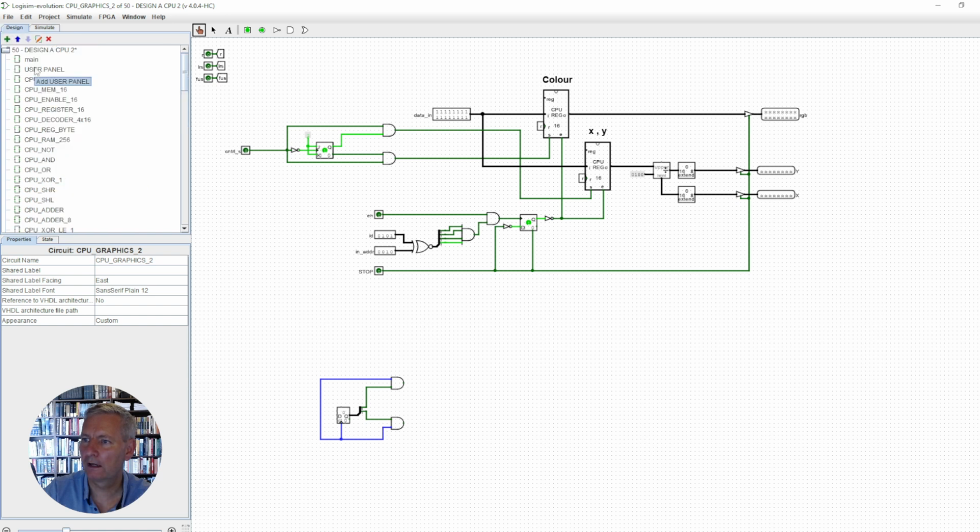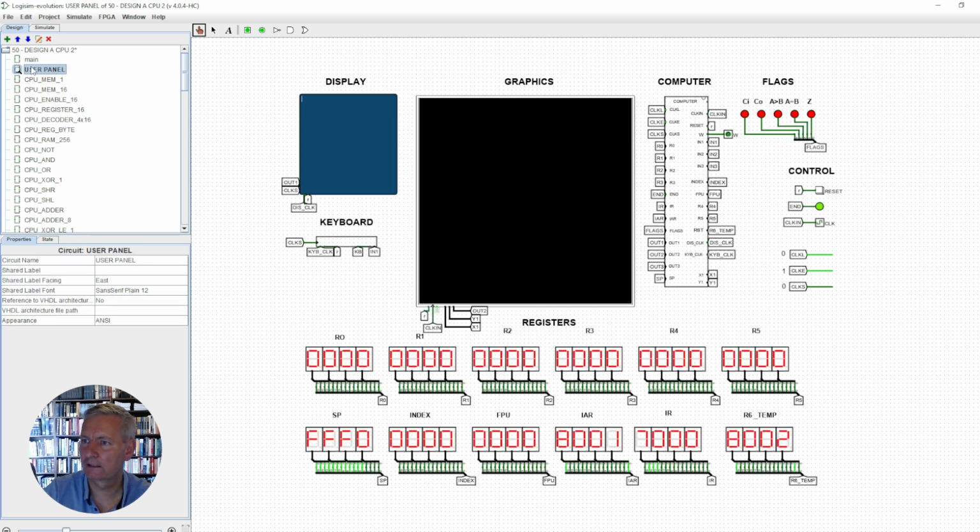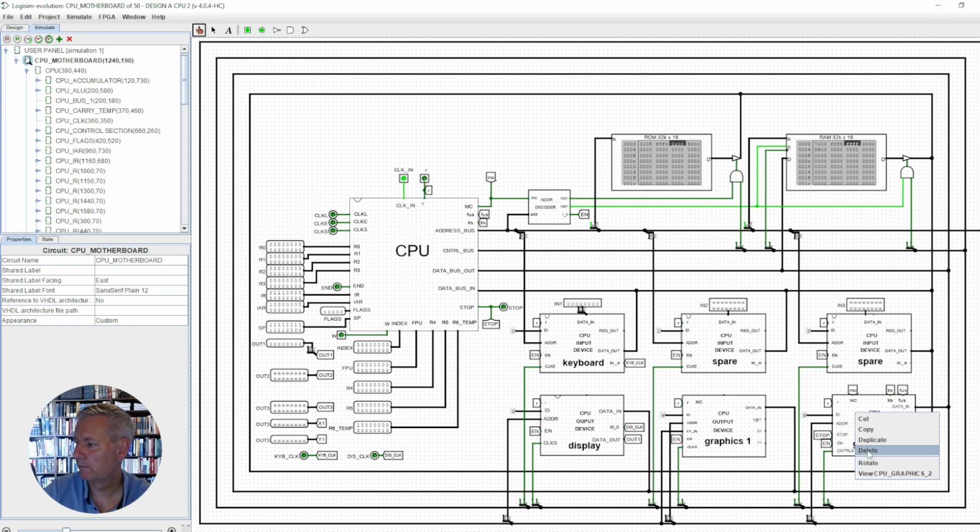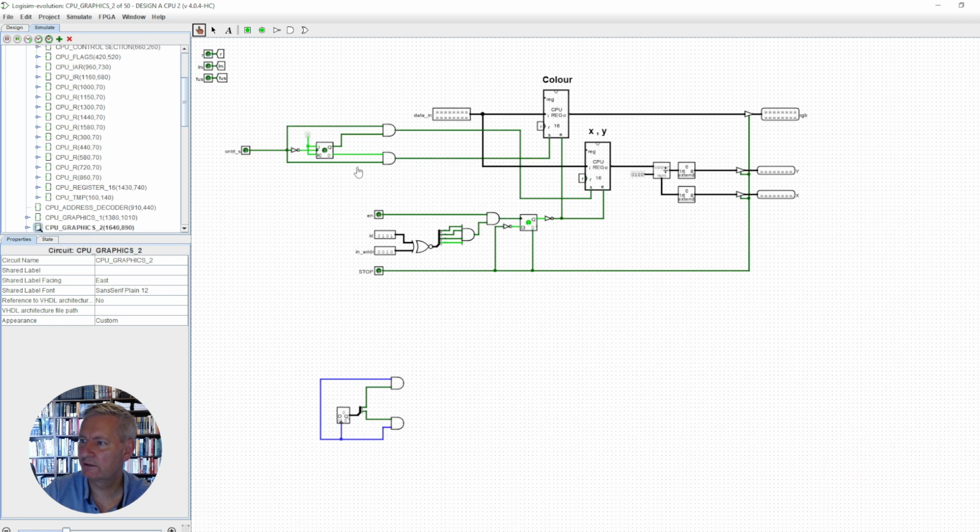So if I come in, we have a high in this line here, and the Q is high. So when I come in this next line here, and I go to this line, you'll see the enable and the other clock L go low. So those have gone low, but the set hasn't changed at all. But when I come in here, you can see that this has jumped from the Q being high to the Q bar going high.